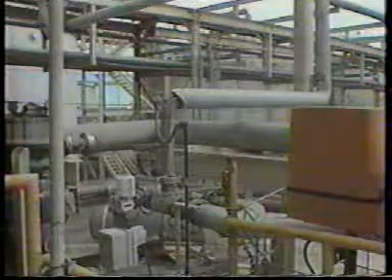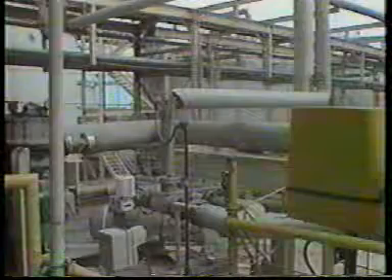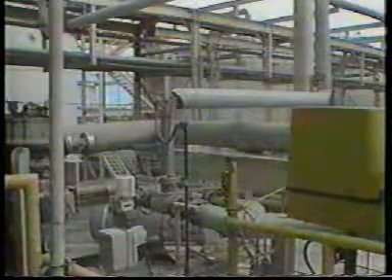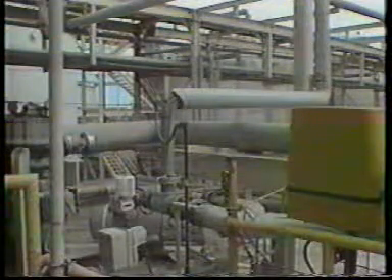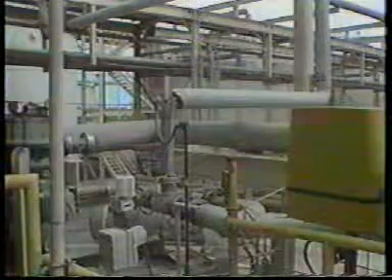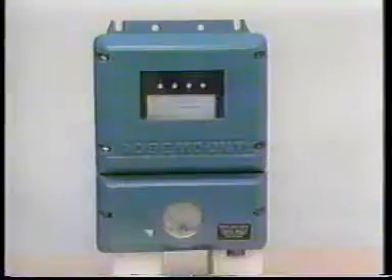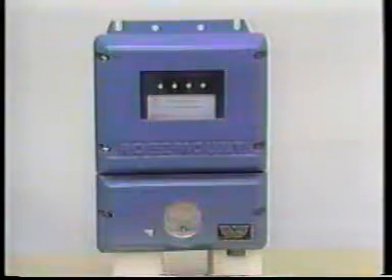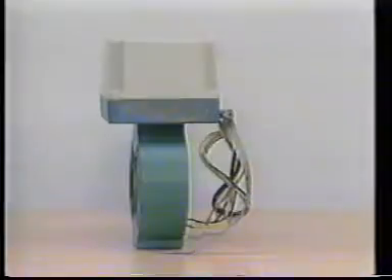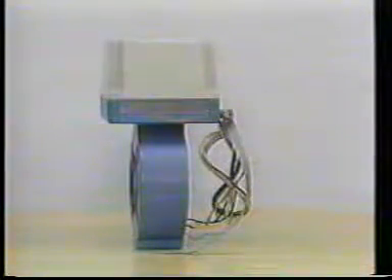Other sources of noise are produced within the meter or the process. The liquid may bear trace voltage, either induced from exposure to a source of electromagnetic interference upstream, or static charge produced by friction as fluid flows. These sources of noise can be partially eliminated by zeroing the instrument with the meter full of non-flowing process liquid. Magnetic flow meters can only be used for measuring flow of conductive liquids. The degree of required conductivity depends upon the design of a particular device and is usually specified by the manufacturer.